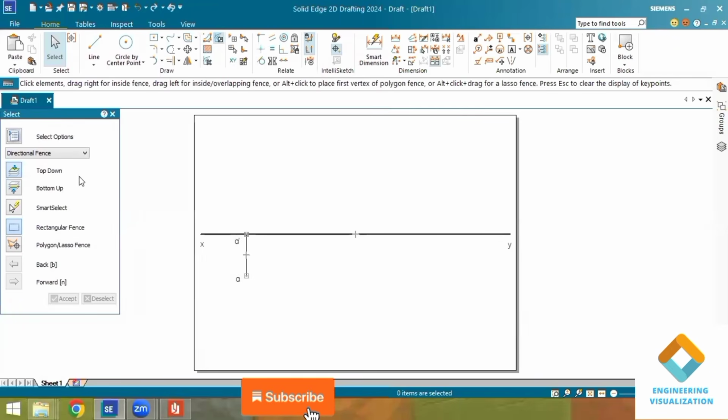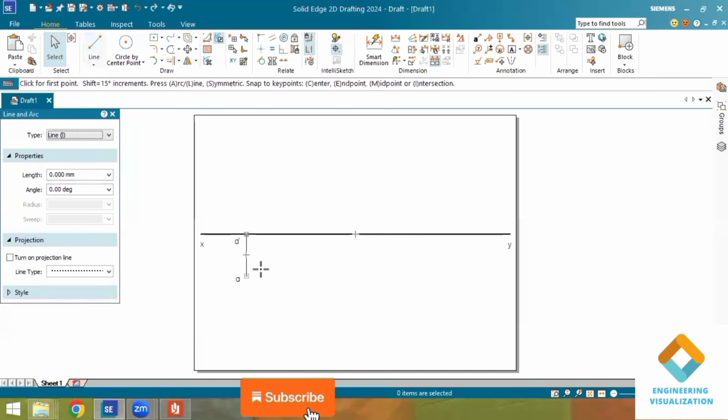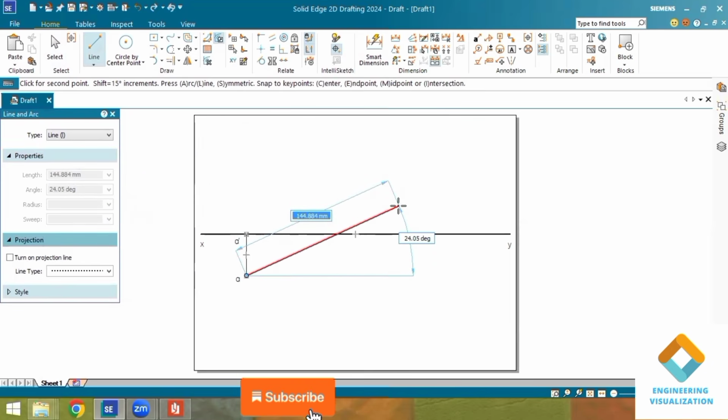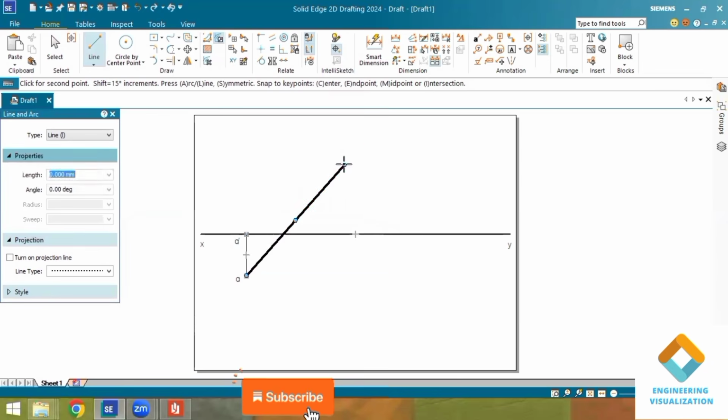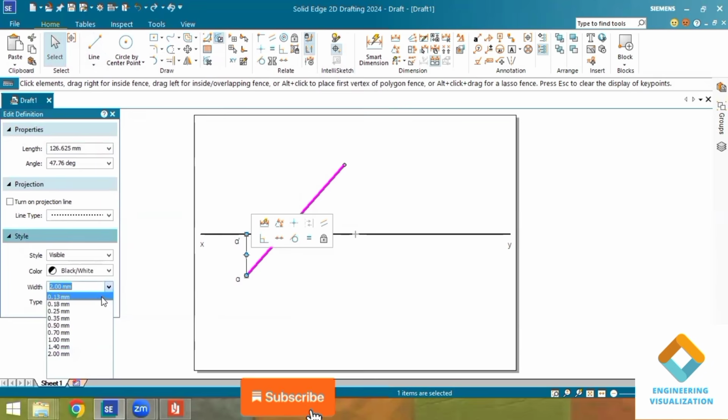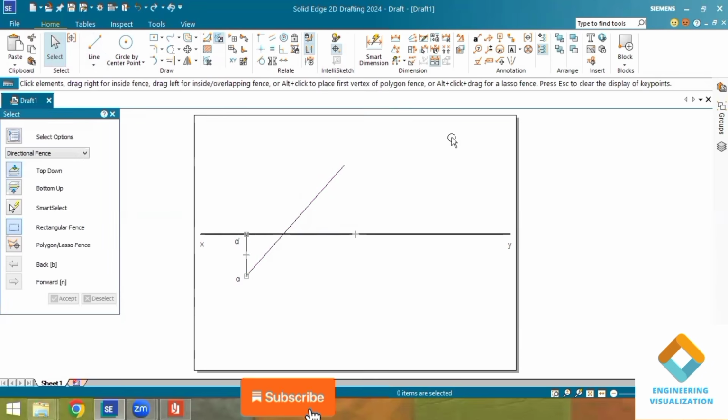So what I'll do is connect the top views at an angle of 45 degrees. From the top view I'll draw an angled line for a length of 45. Just randomly we can draw, and then we can change the angle here. So first I'm drawing one line, and I can change the thickness. Select the line and select its thickness as 0.13. Now here I'll change the angle.